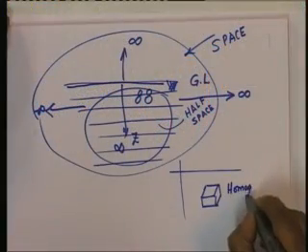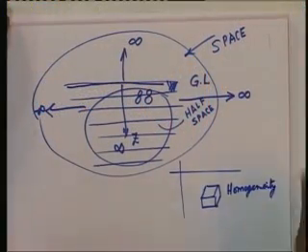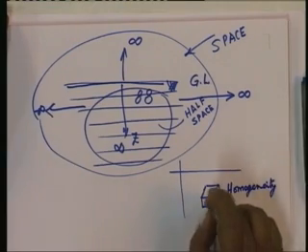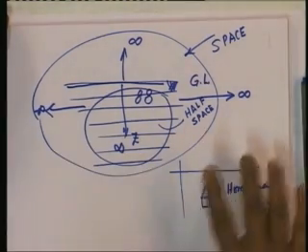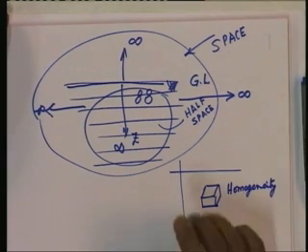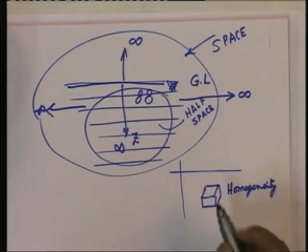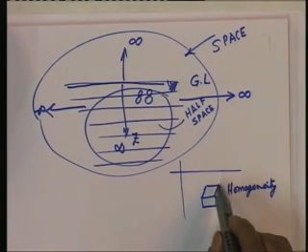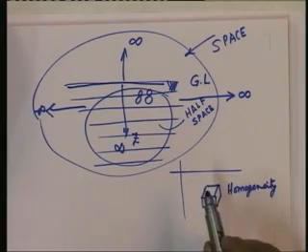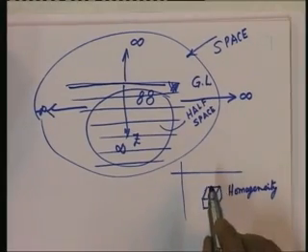So, when we say the soil is homogeneous, we mean that any element of the soil, any element of this continuum is capable of fully representing the behavior of the continuum as a whole, which implies that if we can analyze the behavior of one element from the point of view of stress distribution, we can easily extrapolate it to every other element in the continuum, and therefore understand the stress distribution in the continuum as a whole. That is the importance of the assumption of homogeneity.